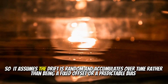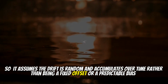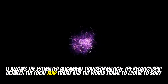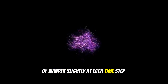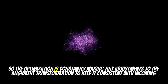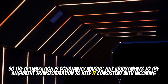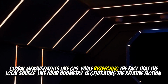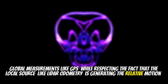So it assumes the drift is random and accumulates over time, rather than being a fixed offset or a predictable bias. Pretty much. It allows the estimated alignment transformation, the relationship between the local map frame and the world frame, to evolve, to sort of wander slightly at each time step. Ah, so the optimization is constantly making tiny adjustments to the alignment transformation to keep it consistent with incoming global measurements like GPS, while respecting the fact that the local source, like LiDAR odometry, is generating the relative motion.